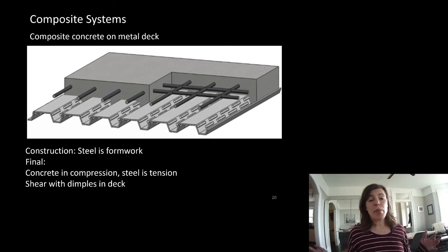So that's really the hard part of the lecture. There's not a lot of math to it. We looked at load sharing for columns and how the load goes to the stiffest path, and that can be dependent on the material stiffness and the amount of the material. We looked at transforming the section, and we looked at the relative merits of load sharing in bending versus composite action in bending. And so we could see that we got a real advantage for bending materials.